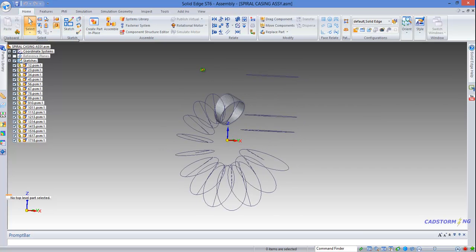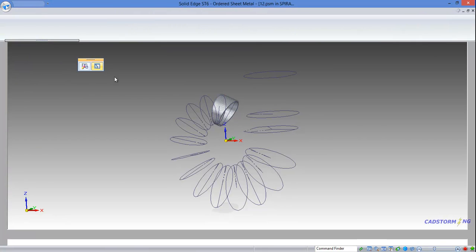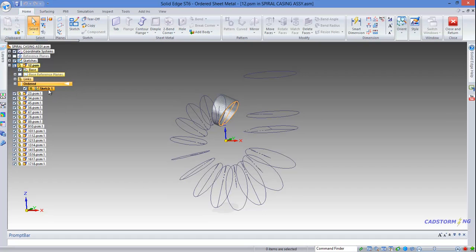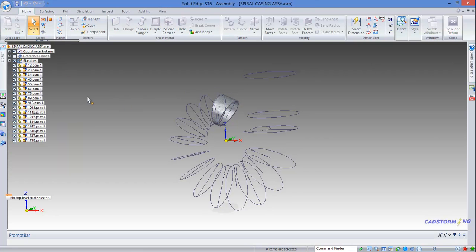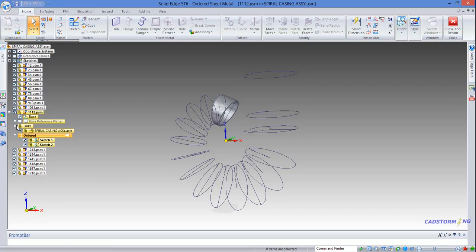And there it is. Now you might want to take some time to go inside each part and make sure that you have the correct sketch link. So this part 1 2 should only have the sketch 2 copied inside, and it seems to be okay. So I strongly suggest you take some time to check that everything is properly copied. The right sketches are inside the right part.